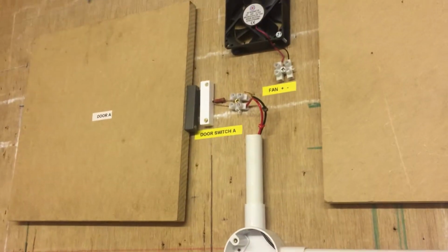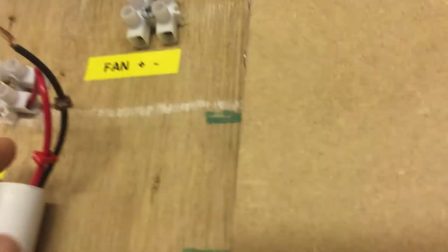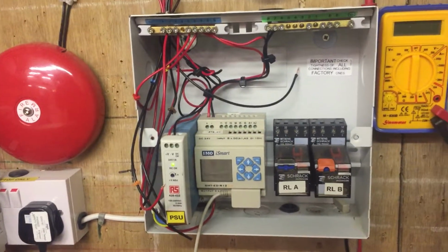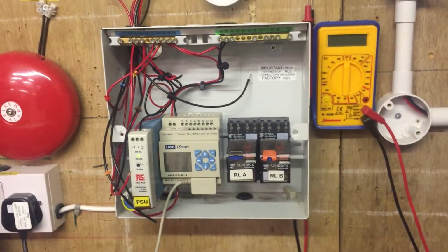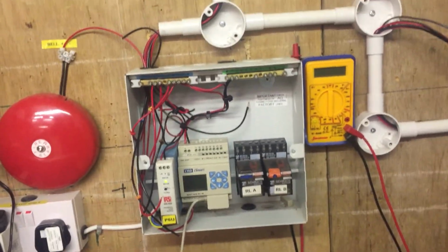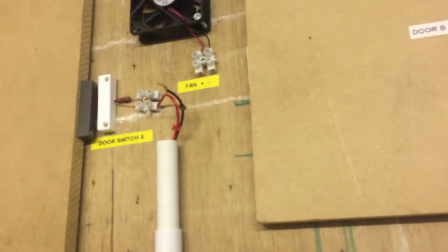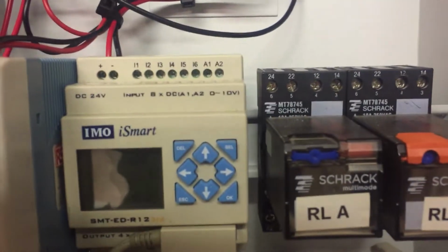We've already wired a positive to each input through the conduit, and we've used little tags on each cable to help identify in the consumer unit which cable leads to where. This avoids confusion. The unit's now going to wire up the black cable, which feeds back from the inputs into the input ports on the top of the PLC.